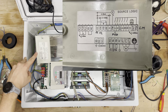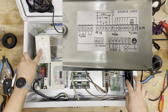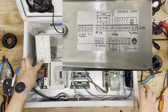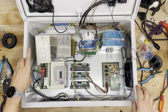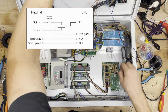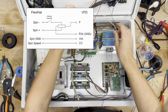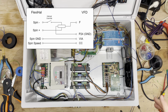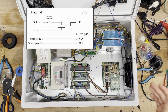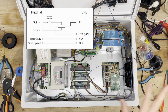I'll control the spindle with the analog 0 to 10 volt output from the controller, as well as a relay to connect forward to ground, to common ground, to turn the spindle on. This was the spindle enable or forward. I still have the manual bypass on the door. I will put the cables just in the enclosure and then we'll do all the cleanup later.